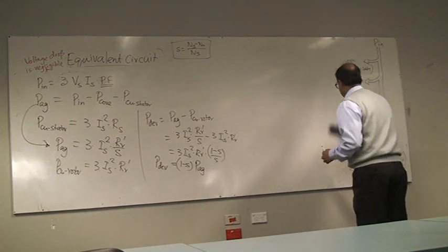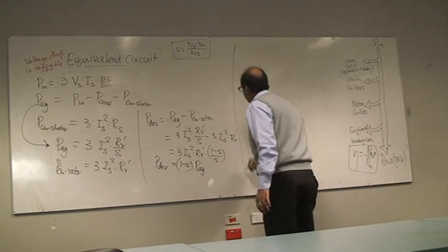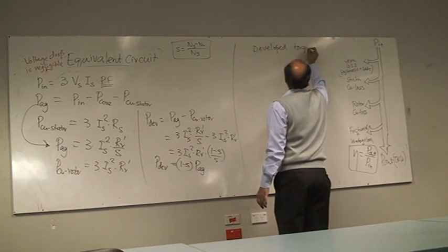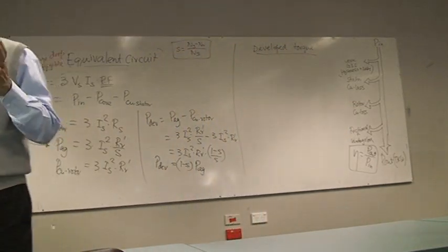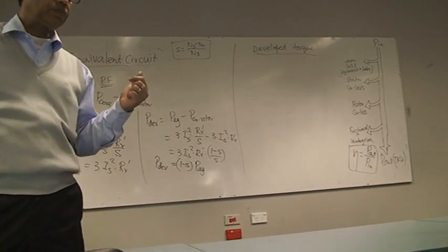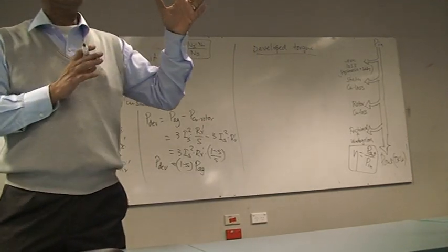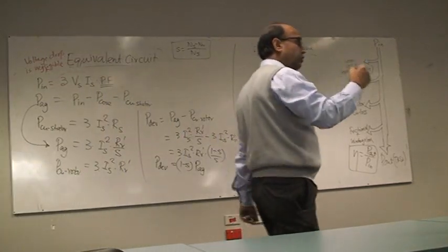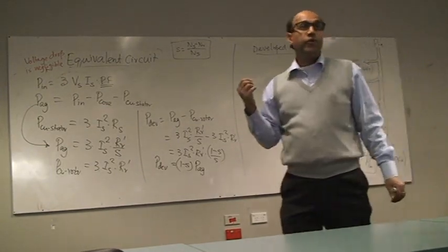So that's my developed power. So what I want now is the developed torque. So I'm interested because in a motor, when you think of any motor, the most important thing of the motor is the torque. How much torque the motor gives, and the relationship between torque and speed. So how the torque changes with speed. Whenever you select any motor, you have to look into the torque speed characteristics. And different motors are suitable for different applications.